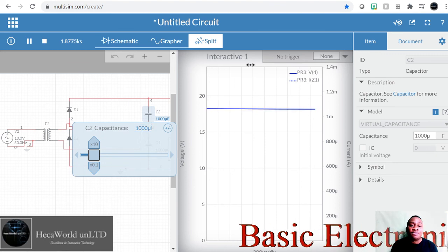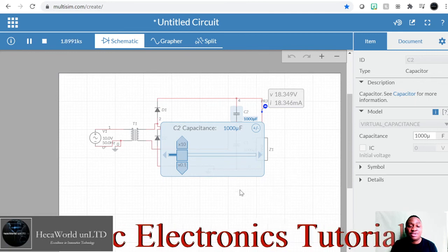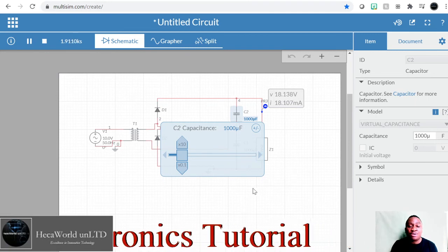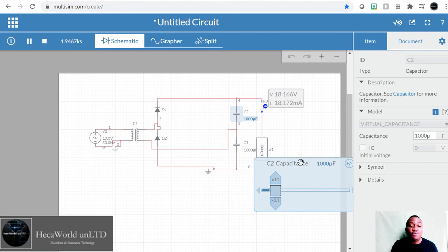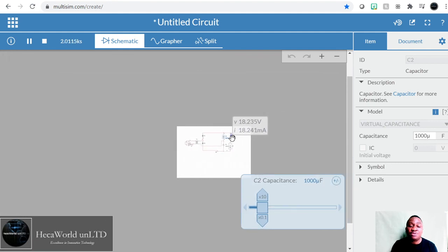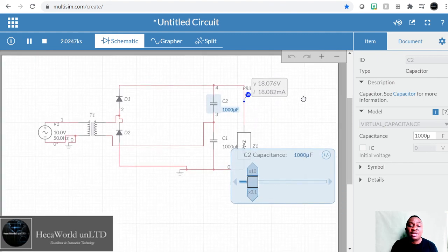So anyways, I think this is an awesome simulator. So I'm going to end it here for transformers. If you have any questions, please post your questions and comments. We're going to see how we can help. Try other forms of rectifiers: full wave, half wave, doublers, quadruplers, and so on. Pick any architecture you like and just try it here, right? And when you do this, remember to put a load at the output. Otherwise, the value might not be the actual value on the output, right?